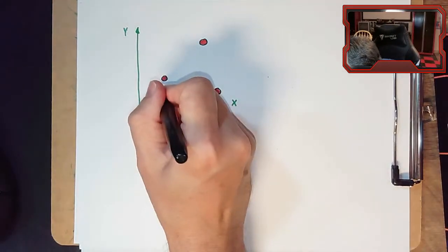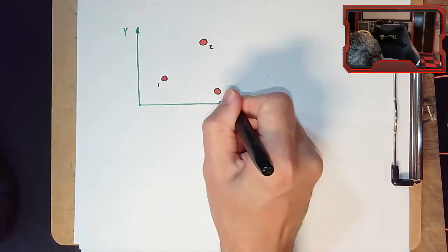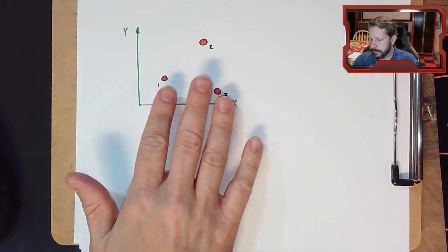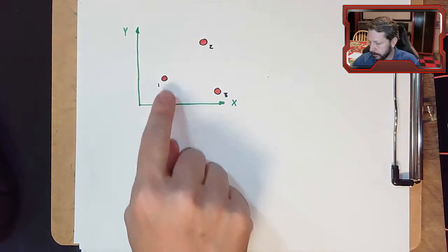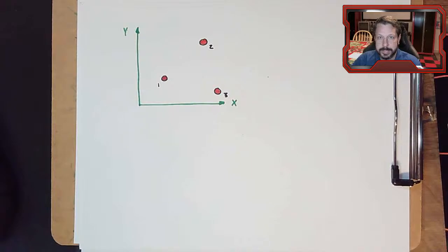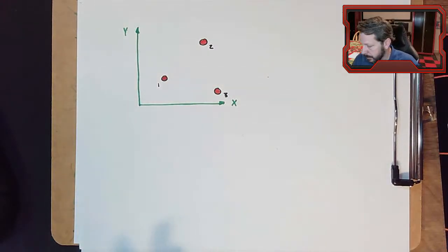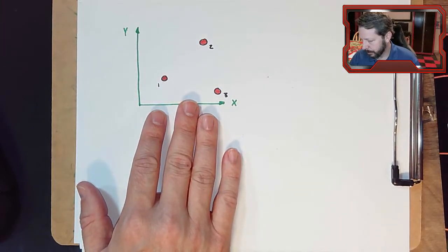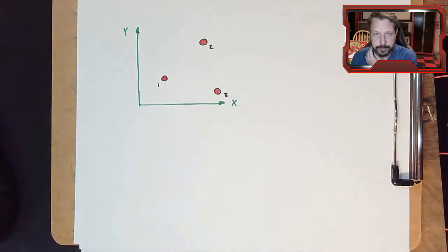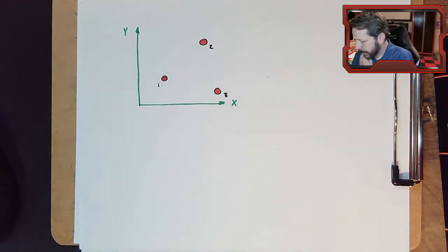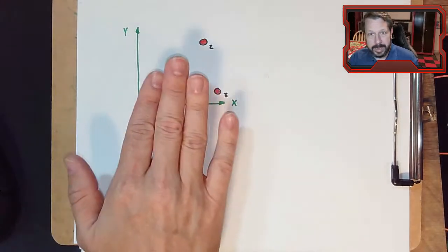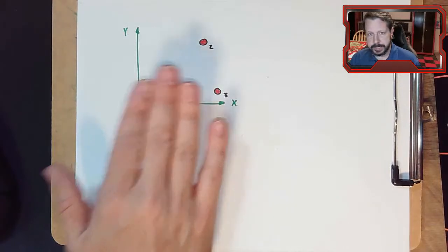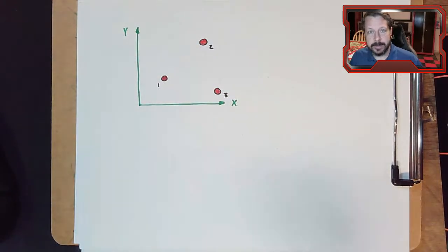And this will be number 1. This will be number 2. And number 3. So the idea here is that I could assemble any pattern of little red dots and clump them all together and make any shape cross-section that I want. But to make it a little simpler without being cumbersome to write all this stuff down, we're just going to have 3 red dots. And each one of these dots is an area, but remember, this cross-section is representing a whole beam or whatever.